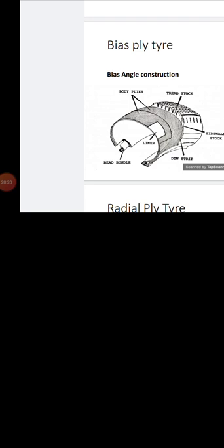Firstly, they have to make the wall strong enough to contain the air pressure and yet leave it as supple as possible for deflection also. And secondly, they have to support the treads. And these two requirements conflict with each other, because to obtain sufficient bracing of the tread, the ply must be reasonably stiff, which then means that the wall has to be rigid also.